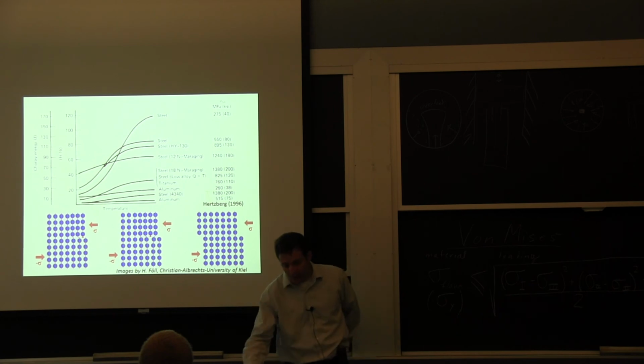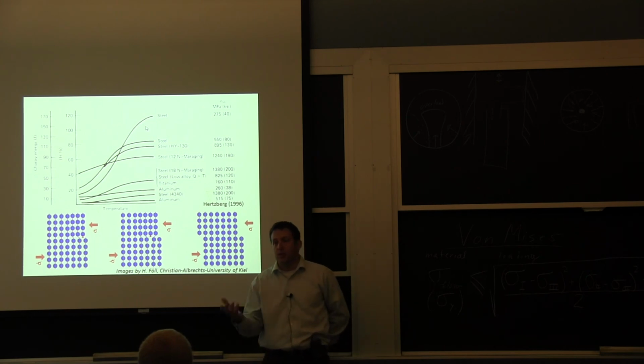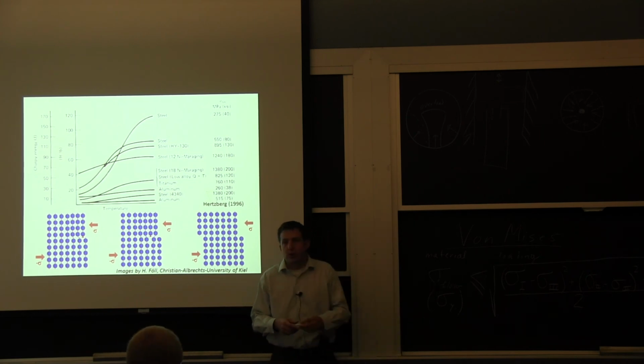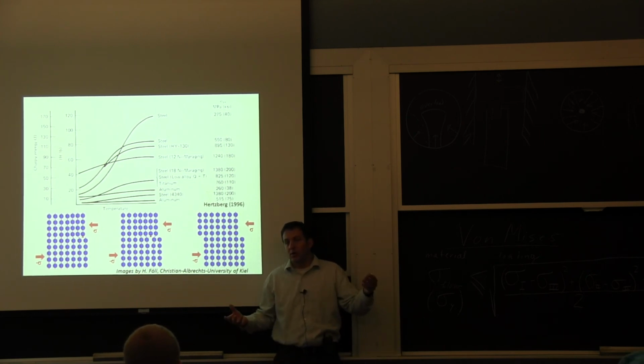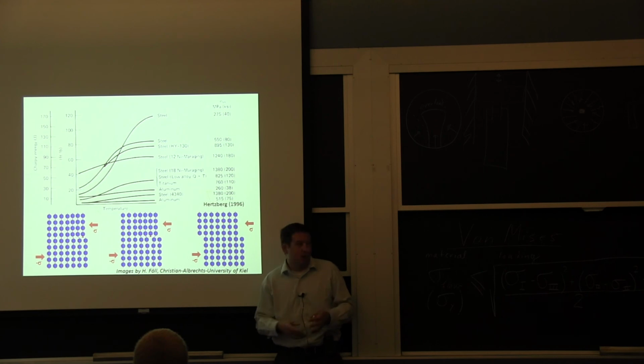So if we look here at a high temperature situation, the lower strength steel will give you the higher energy. Because you have a lower yield strength, you're going to be able to deform more before you reach the fracture condition. It gives you more distance.